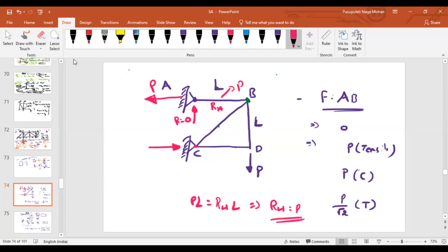Could you explain once again, please? This is a vertical reaction, isn't it? Imagine this vertical reaction also you don't know. Let us say this is R1. These two are passing through the same line of action or not? Will there be any moment generated because of these two forces? No, equilibrium.